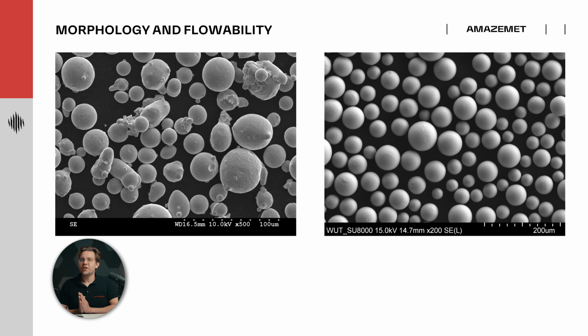In the case of an ultrasonic atomizer, there is no supersonic jet. There is no way that two particles will collide and stick together in the atomization process. That's why it's much easier to get satellite-free particles in an ultrasonic atomizer, particularly rePOWDER, than in a gas atomizer.